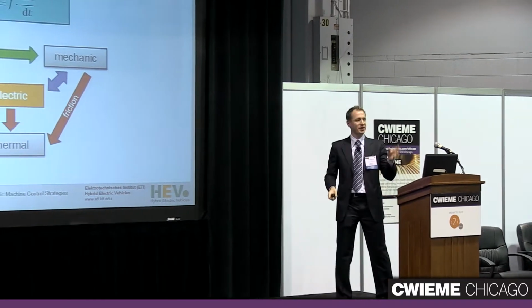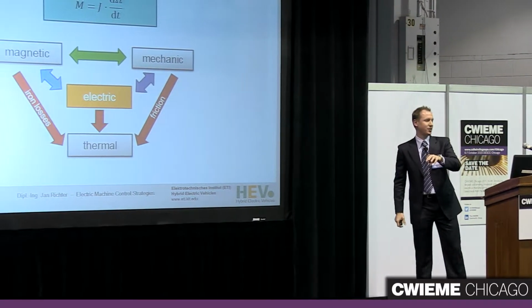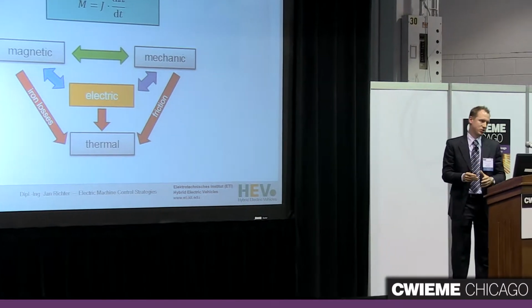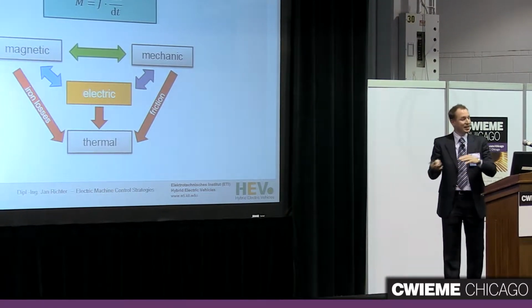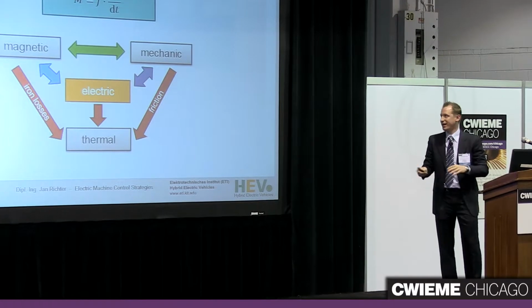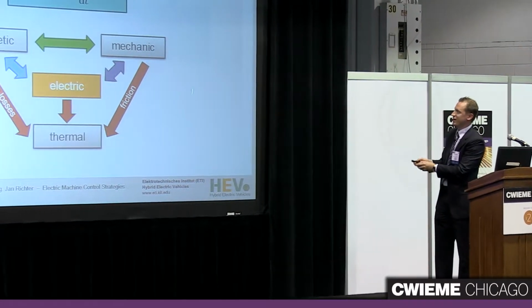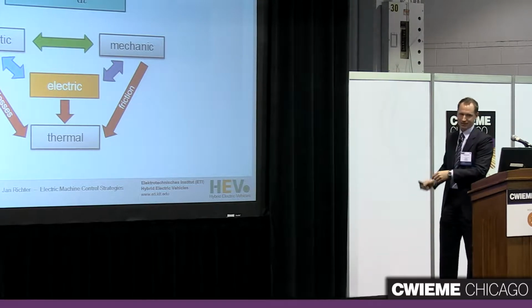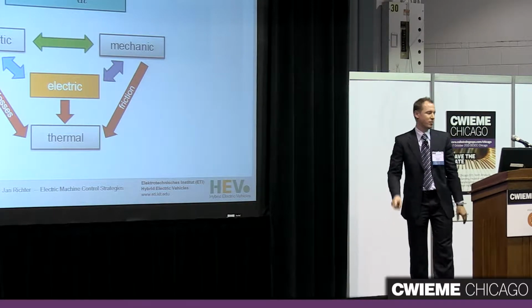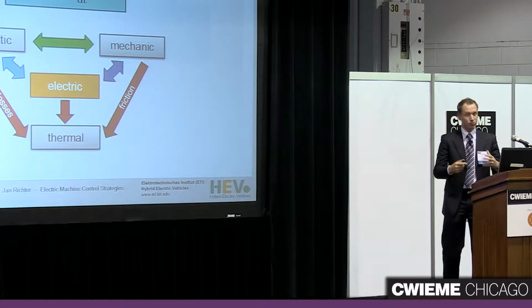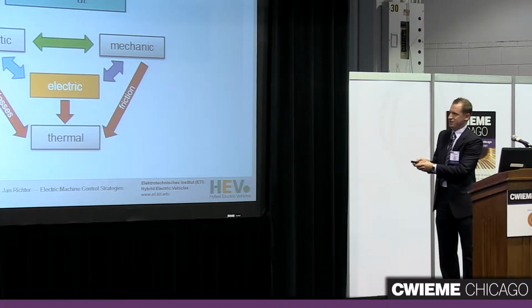You can also transform magnetic energy directly into mechanical energy, and the other way around. But this effect only occurs if you take spatial harmonics into account. Because we neglected them. This was one of my assumptions. I cannot cover this really. Just to make it complete, I like this picture. This is what any motor would look like. So whatever book you read, whatever presentation you see, whatever paper you read, doesn't matter. It's only a mathematical rephrasing of this picture.